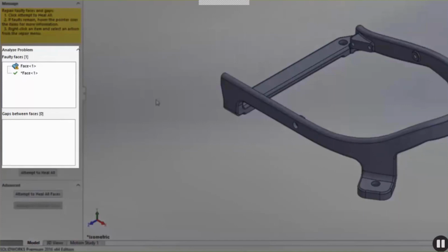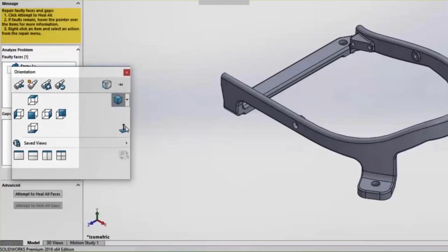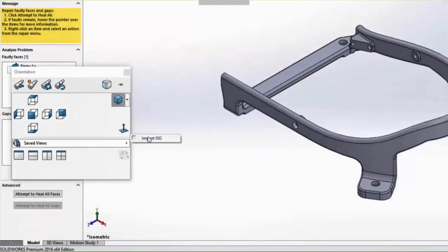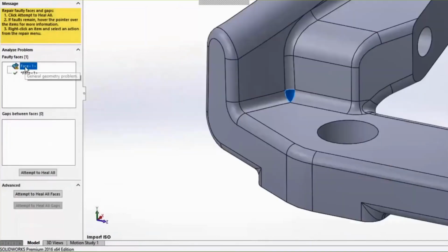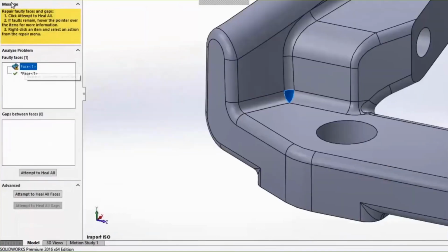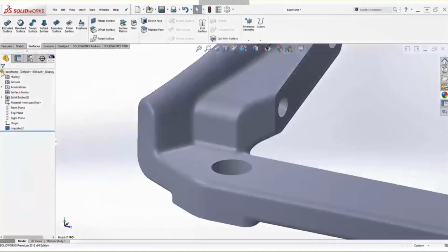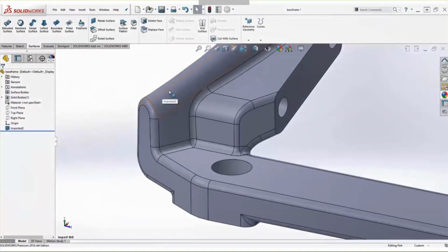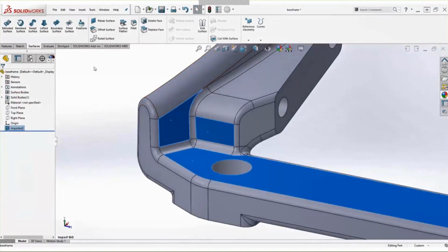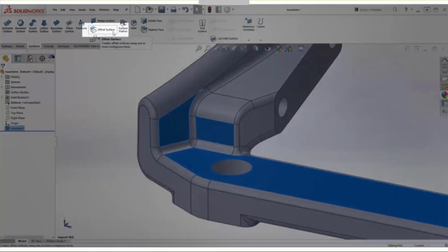So let's take a look still at this example where we've got faulty geometry. And we can see the problem here is where this blend comes together, where these three fillets all meet together. So to rebuild the fillet, we're going to need to rebuild that original corner. And to do that, I'll make copies of what I like to call the hard geometry.